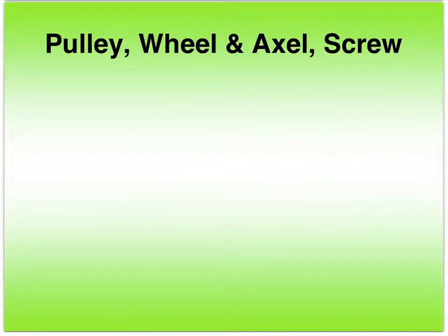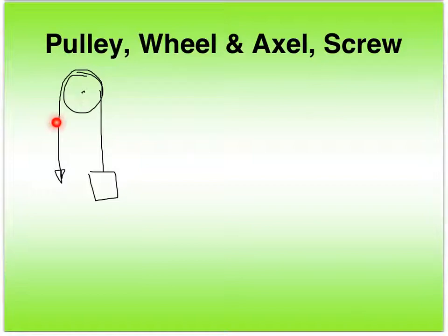Okay, a pulley is a simple machine that can do multiple things. The first thing that a pulley can do is change the direction that you're trying to move something or trying to apply a force. Let's say this is my pulley, and I have attached to it a weight hanging down. What that pulley will do is extend the rope around the pulley and come down this way, so I can apply a force downward to lift the crate. So I can use maybe my own weight downward to lift the crate upward.